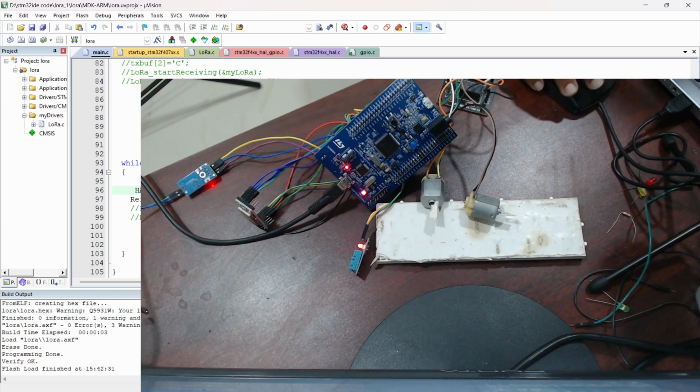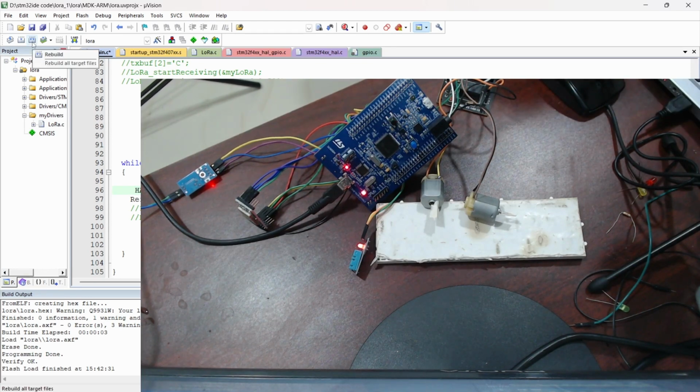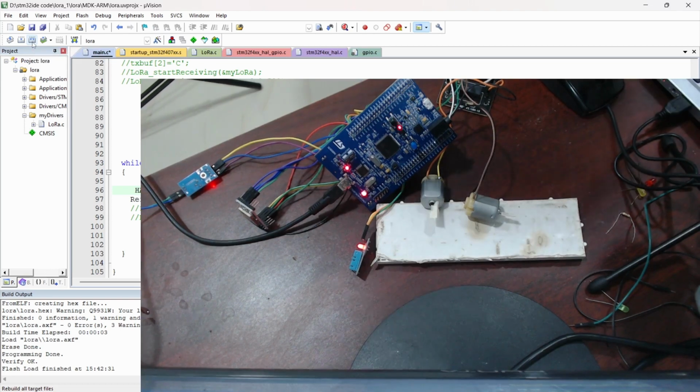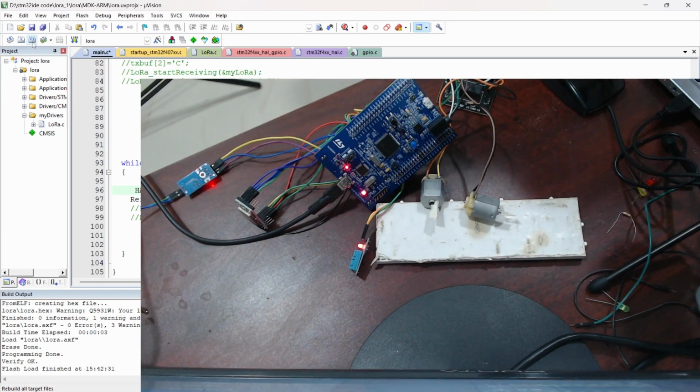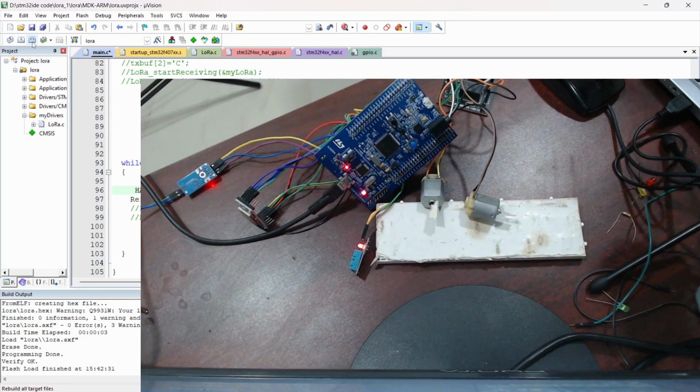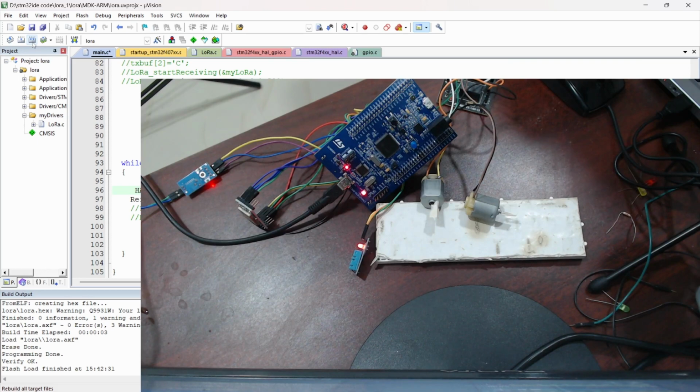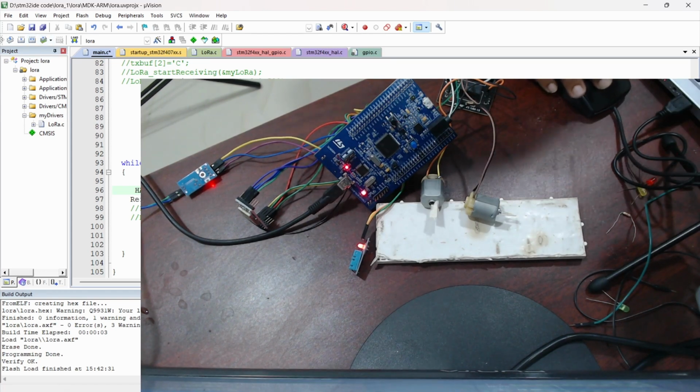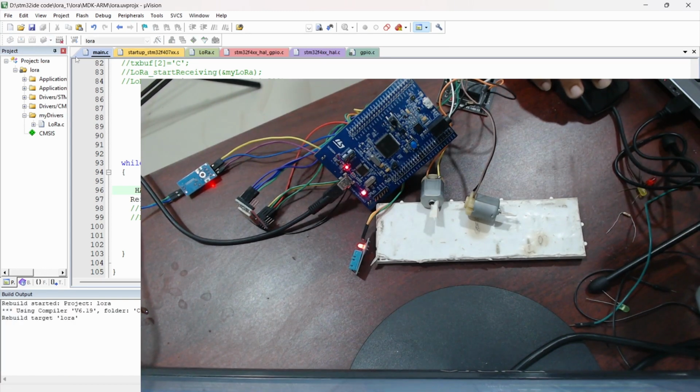Okay. So we will change this again to 80. If there is no error in the loop of proceedings, the LED will not be turned off and the watchdog timer will not reset the controller. If there is an error in the execution of the int main code and it is stopped at some line, then the watchdog timer will exceed the timeout and it will automatically reinitialize the controller. So this is used to fix our bugs without the user interface. So we will again change this to 80 microseconds and we will see.